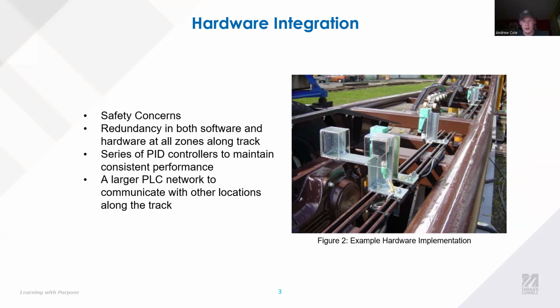So on the software side, you want to make sure that your control systems can handle the wide variety of loads that they're going to be facing, whether it comes to different distributions of mass, different amounts of mass on each of the individual trains, just making sure a variety of these factors can be handled by your control system. And the same goes for the sensors, specifically with the optical ones. You want to make sure that every time a train does pass through an optical sensor, that the sensor is reacting to that. That way you can communicate with the other sensors to let them know what's going on behind and ahead of them. Again, redundancy on that safety.